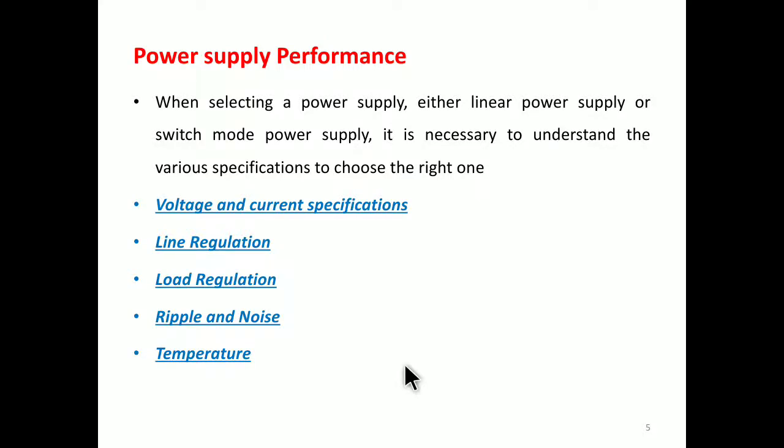When selecting a power supply, either linear mode power supply or switched mode power supply, and some of the parameters to be considered, it is necessary to understand the various specifications. So before that we have to check the specifications. What are the specifications? The voltage and the current specification, line regulation, load regulation, ripple and noise, and the temperature. Let us go through them one by one.